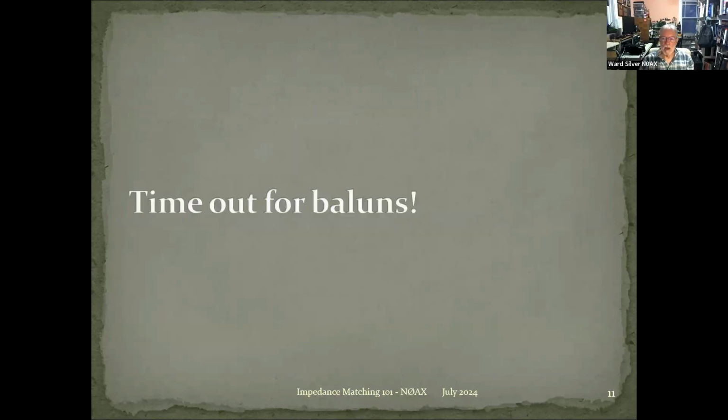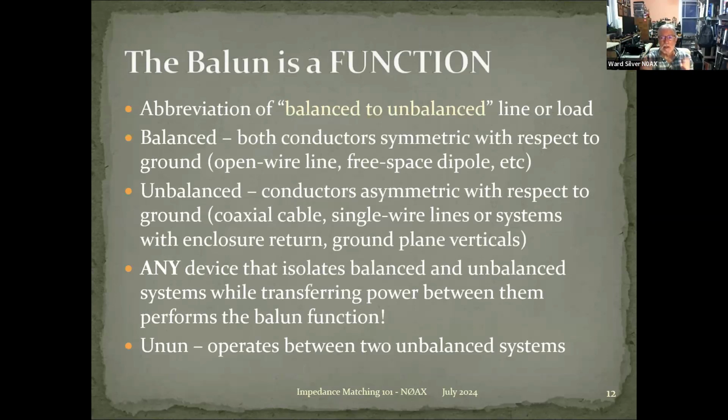Let's take time out to talk about balance. Okay, this is a big topic for me. A balun is a function. It's not just a device, it's a function. And balun is an abbreviation of balanced to unbalanced. And that can apply to either the line or the load. The line can be balanced, the load can be unbalanced, or vice versa.